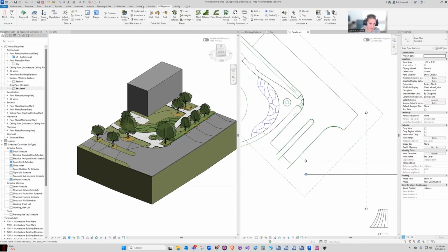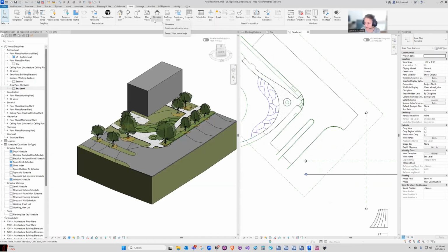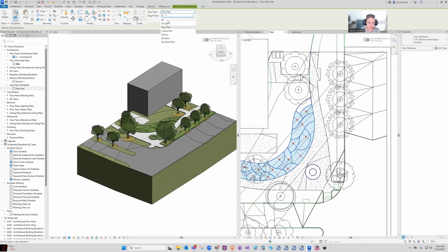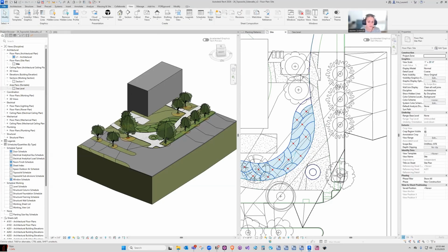But the main thing is if you have an enlargement plan and you want to put a view reference to your area plan, that's not an option. If you have an enlargement plan with multiple sectors or multiple enlarged plans and you want view references to that planting plan with areas, it's just not possible, which seems very bizarre to me. Area plans are basically not really intended to be part of true documentation. So that's the main downside to using area plans and why I've switched to using